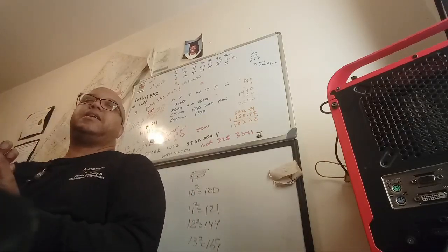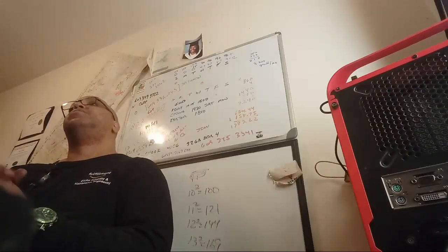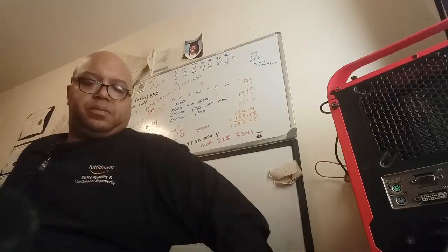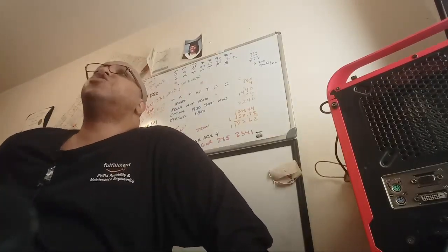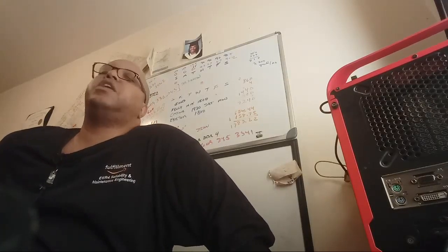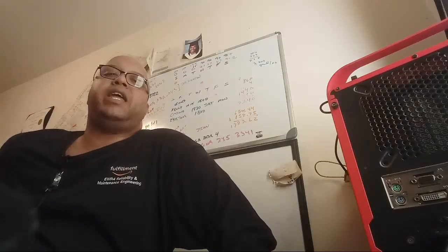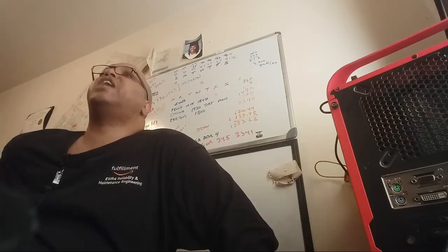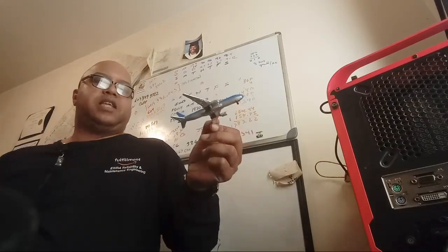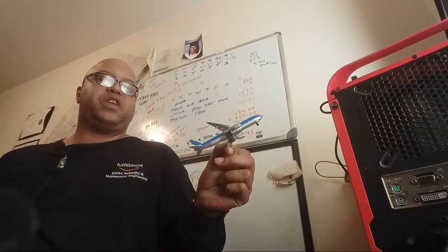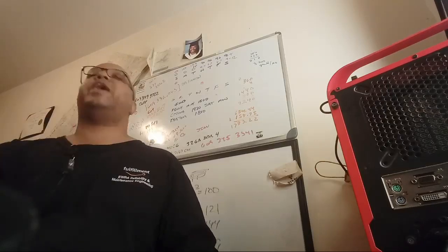What is another configuration an aircraft could be in? Well, I'm going to give it the informal name, the tail dragger. Very good, the tail dragger, and we call that the conventional landing gear. Two main gear up front, and you have a steerable tail wheel. The reason they call it a tail dragger is because a lot of times when you see these aircraft, they're tilted, like their nose is pivoted up towards the air because their tail does the steering, and hence tail dragger.